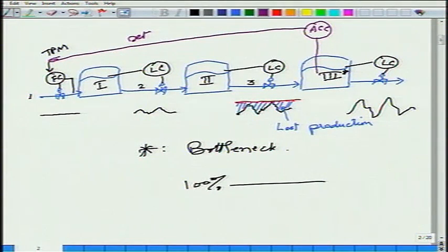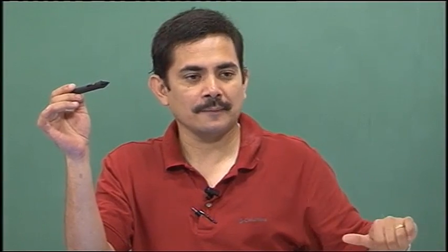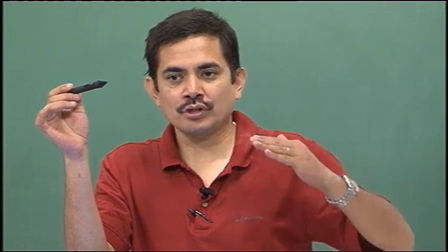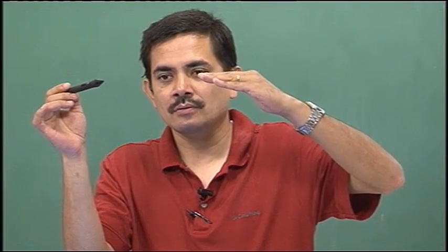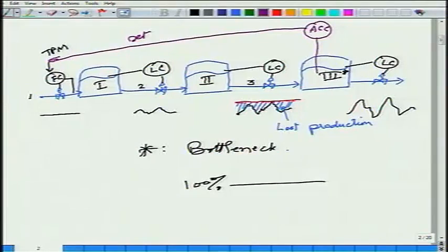This is what the operator is doing, right? He is looking at the active constraint. I am far away from the constraint being active, jack up the throughput, right? I am approaching the active constraint value, well, reduce the throughput. Violation is not acceptable, because what that means is then unit 3 will have to be shut down, and if unit 3 has to be shut down or some corrective action has to be taken, that represents a significant economic loss. Okay. All right.